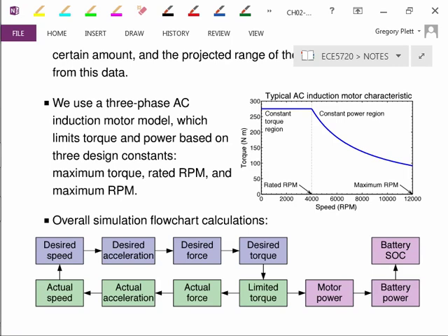You could have a DC magnet motor, you could have an AC induction motor. There's different types of motors. This one hasn't been used so much to date because of the power electronics being expensive, but we expect that as demand goes up, the electronics prices go down, as is typical for electronics, and that these will end up being less expensive and give better performance than a DC motor. DC motor also requires a permanent magnet, which uses expensive materials found mostly in foreign countries, and so that has some automakers concerned about their use. In any case, we could use different models.